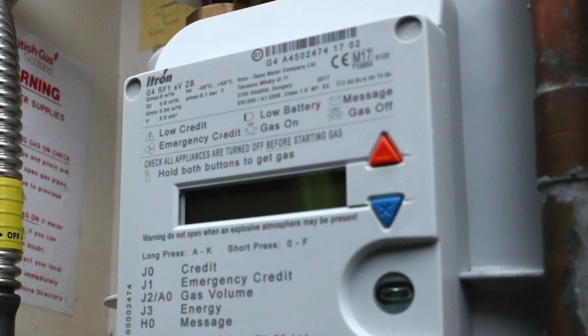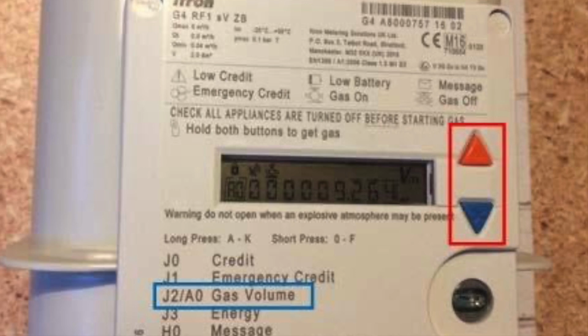Once we've hit this 2 minutes, we can take the second reading, what shows on the display, and this will now give us our first and second reading. We can now use these two readings to do our calculations. So take your first away from your second, times it by 30, times 38.7, divide by 3.6, divide by 1.11 will give us our kilowatts net.